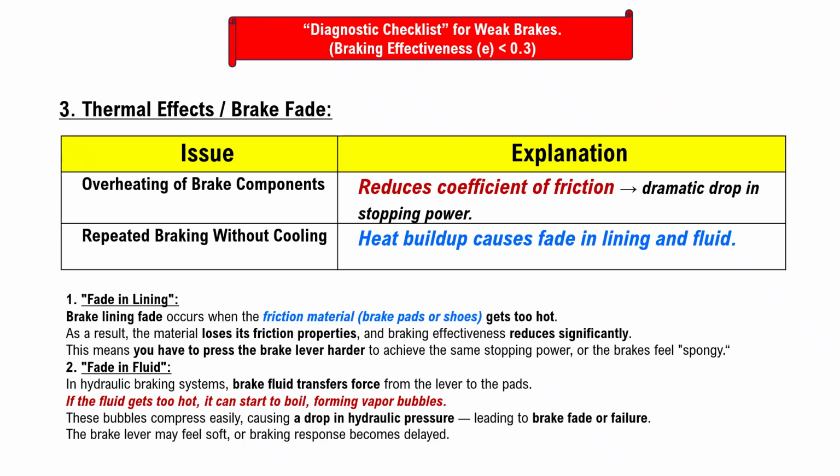Issues related to thermal effects. Number one, overheating of braking components. Overheating reduces coefficient of friction, which results in dramatic drop in stopping power. Repeated braking without cooling. In this case, heat builds up, which causes fade in lining and fluid.